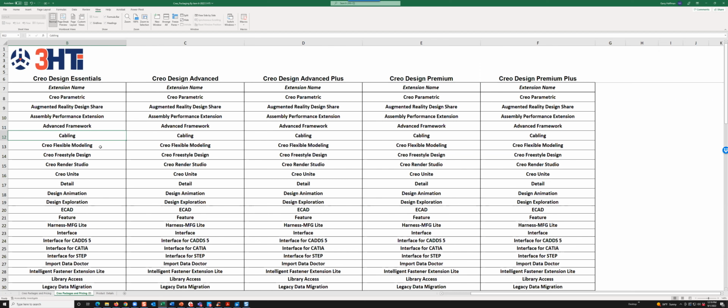It allows you to put parameters on different types of features and modify features individually, but it does not give you a full feature tree. But nonetheless, I think when you get into parametric modeling, you can ultimately build a house of cards if you don't know what you're doing. And this gives you the ability to change imported geometry, and it gives you the ability to make last minute design changes when sometimes the feature trees become very, very cumbersome.